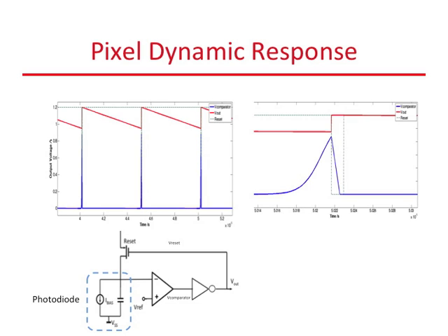The switching output of the comparator passes through an inverting buffer and turns on the reset switch. The reset switch charges the capacitor back to VDD. As the capacitor voltage increases, the comparator switches high. Once again, the switching output of the comparator propagates through the inverting buffer, and after some delay depending on the buffer capacitance, the reset switch is open-circuited once again.